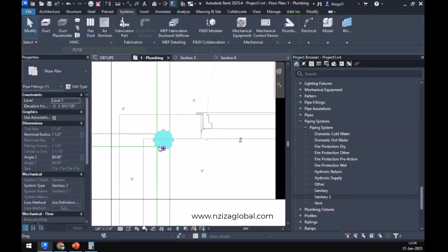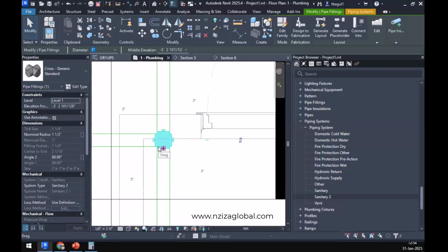If you have this kind of connection, a 2-point connection, double Y connection, the elevation will be a bit hard for you to inherit because there is one Y connection and you're trying to tilt it at one location. It might give you some issues. I have had conversation with Revit folks and this is something that they are working on. It is still something that is being worked on. But one point is there that we need to have a double Y connection.